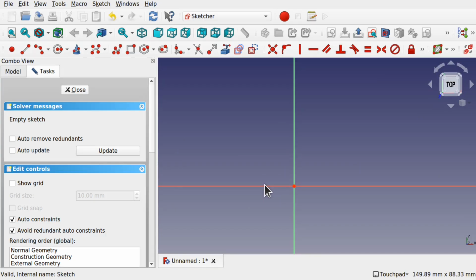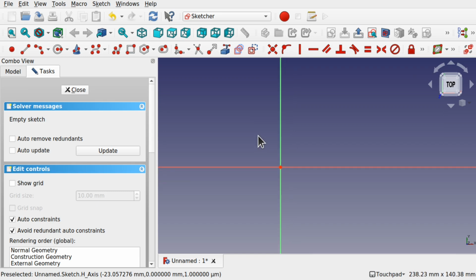Now the good thing about the Lattice2, there's a number of tools to actually allow for placement. There's one of my favorite tools in there, and if we remember back to the previous video I did with the placement in the part design using the lattice pattern, we created a sketch for placements. There is another way of doing this which is far more flexible when you're using something like the part workbench, the curves workbench, or any of the other workbenches. It can be used for booleans, cuts, etc. as a standard lattice placement.